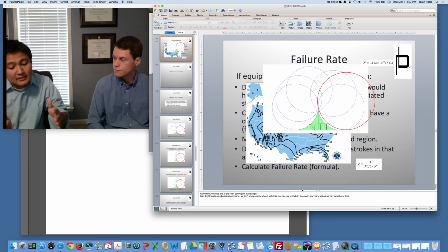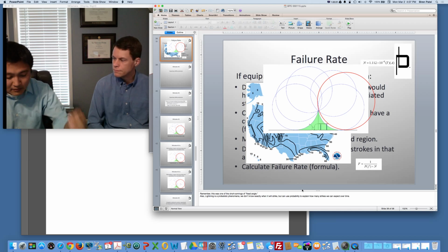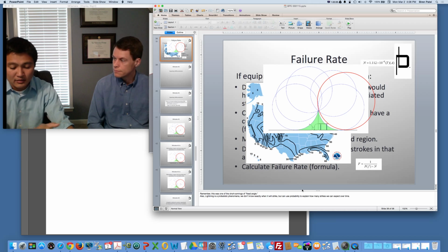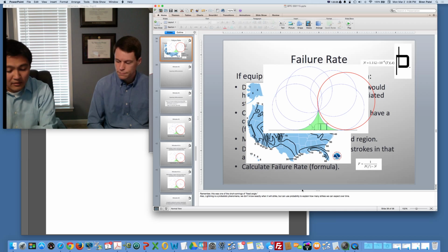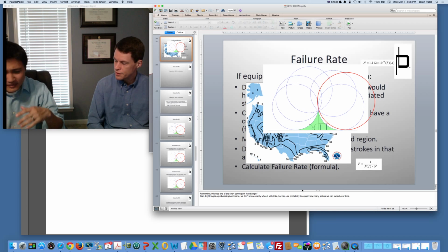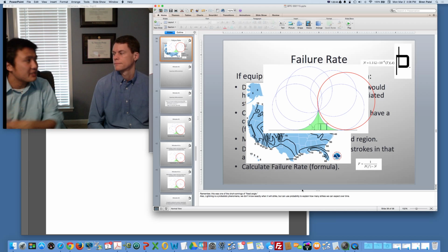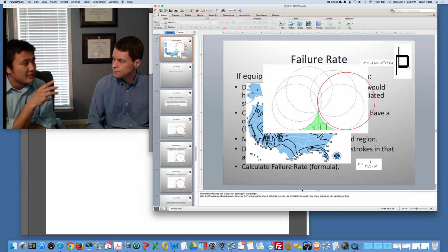Generally speaking, I like to say, define at least 2, if not 3 categories of priority substations. Priority 1, our top priority substations, cannot go down. We need to have 400 or 500 years between failures. And then you may have priority 2 and then priority 3, priority 3 being the lowest priority. If these things go down, there's a lot of backup. It's not going to cost us a lot. We'll accept 1 failure every 100 years. That makes sense.